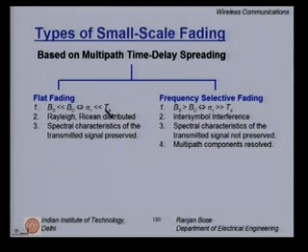For the same signal that we are sending, if the time delay spread increases, in that case the channel will tend to become more frequency selective. The other feature of a frequency selective channel is that the spectral characteristics of the transmitted signal is not preserved. This is a major impediment.